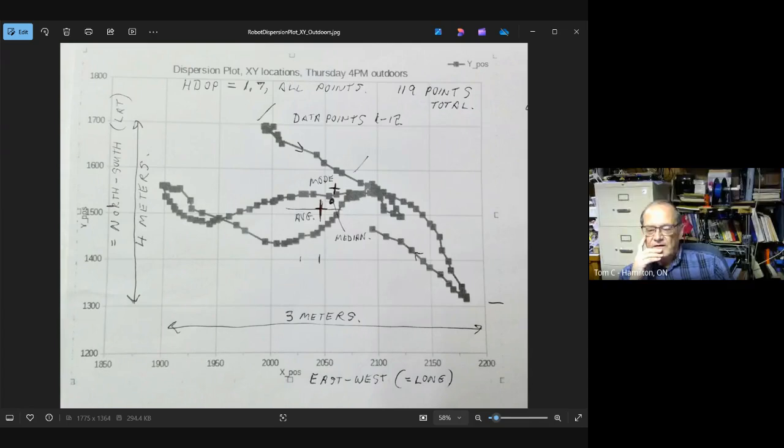Okay. So the next question I have is, I am using the stock antenna that comes with a 6M when you buy it from U-Blox or its distributor. I note that there are other antennas. I see most of you using other antennas. I see some discussion of other antennas, and some discussion of ground planes to mount the antenna on, including a very excellent white paper by U-Blox about antenna grounding. Basically the ground plate that you sit the antenna on. I do not have any of those ground plates. My antenna happens to sit on a little metal plate that's not much bigger than the antenna, but that's not really much of a ground plane for purposes of preventing the backscatter interference, as I understand it.